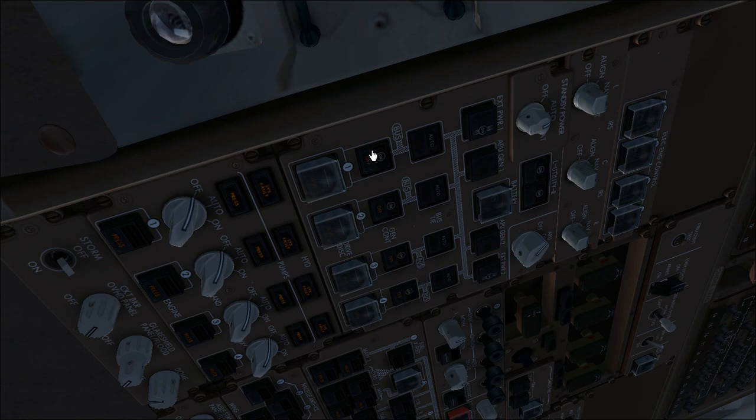This is because they are actually disconnected from the engine at this moment. They are not running, and you also have to check that the drive lights in the drive disconnect switches are illuminated. Be cautious, because if you press one of those buttons, the generator will be physically disconnected from the engine, and you have to call the maintenance and engineering part of the airline to reconnect the generator shaft to the engine accessory gearbox to make it move.